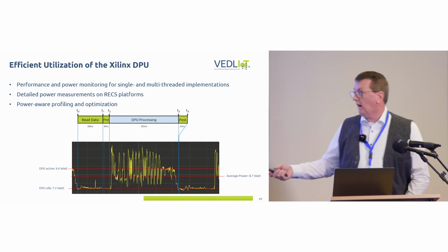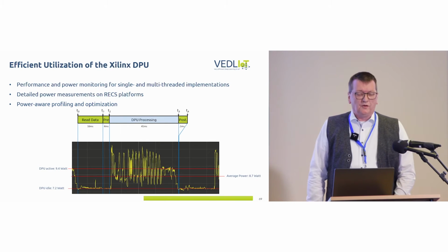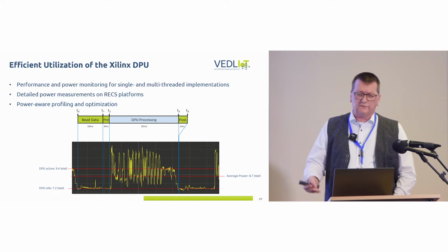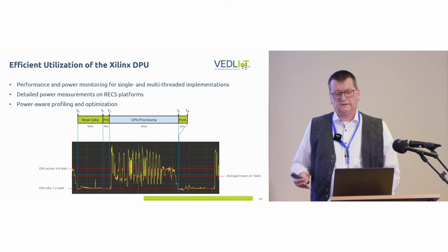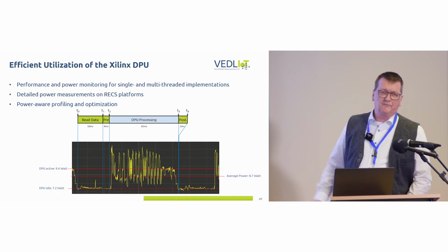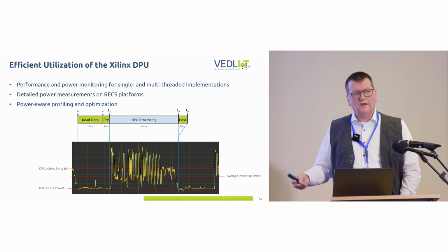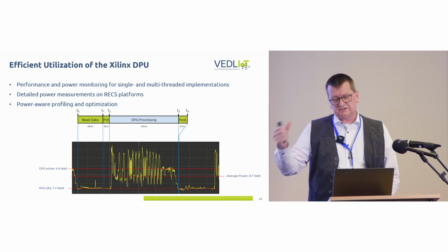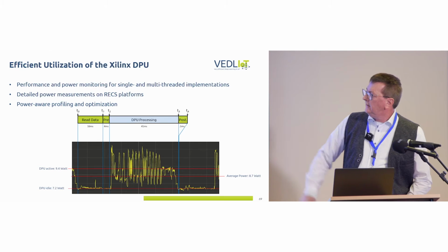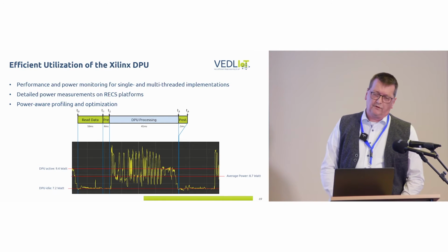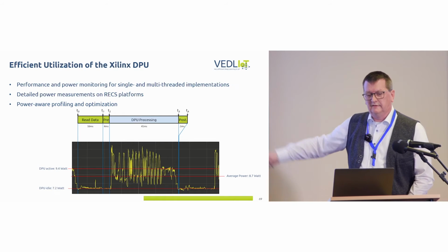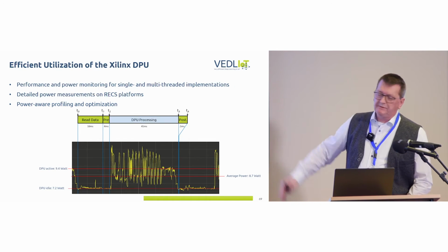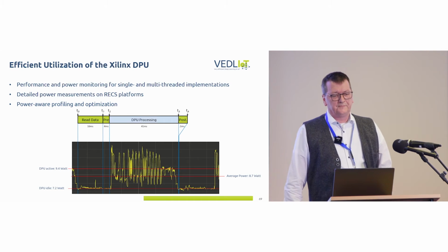And then we measure the power. That's interesting, not only to see how well we do, because we know exactly the power, but that's also interesting from a profiling point of view, because now you can really see when something is happening. And on FPGAs, that's quite nice. You can have real timestamps showing, well, now I'm starting this operation, now I'm starting this operation, and this can be indicated here also clearly. So, for example, the nicest pictures you get if you do this simply without multi-threading, then you can exactly see when the GPU processing starts and so on.